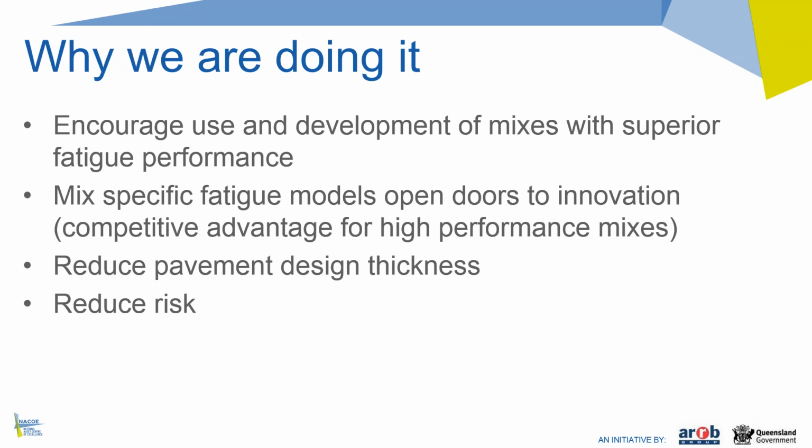And at the same time, I would again argue that this is reducing risk, because instead of using this general model that was developed for 12 mixes in the 1970s overseas, and those mixes have very little in common with mixes currently used in Australia, we're actually testing the performance of modern Australian asphalt mixes. And again, we're creating here a direct link between laboratory mix design and field performance. So this is again a performance-related design method.